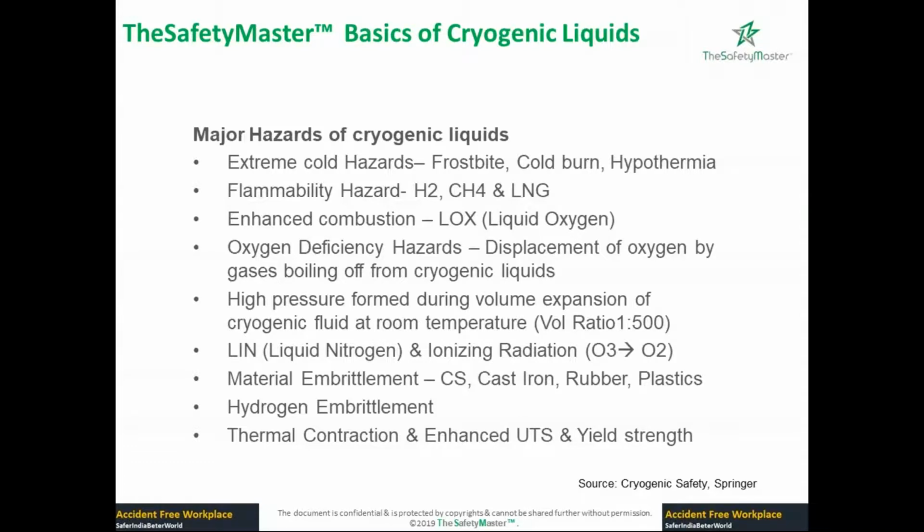If there is ionization radiation around that particular place, the oxygen will form O3, and then when O3, that is ozone, converts to O2, it will give an explosion. This is a very specific ionization radiation hazard peculiar to cryogenics.